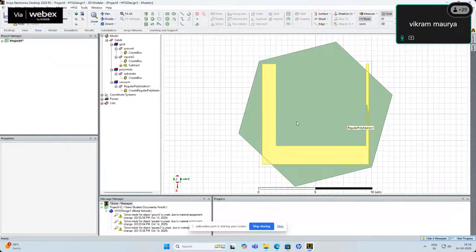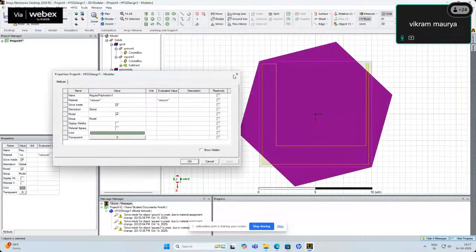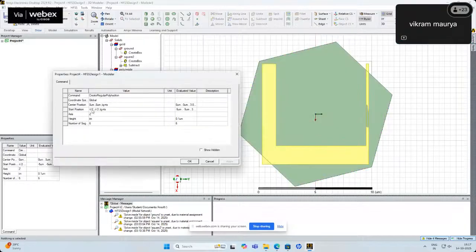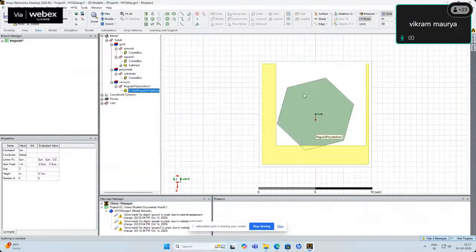Now, as you can very clearly see that this is very much exceeding the limit of the substrate, because it is exceeding the height and all that. The radius is very much larger than 10 micrometers. Okay, so we can change it simply by, let's say it is instead of L by 2, I can say it is L by 4, and then I put OK. Now we can see that the hexagon is very much confined on the substrate. It is not going outside of the unit cell.